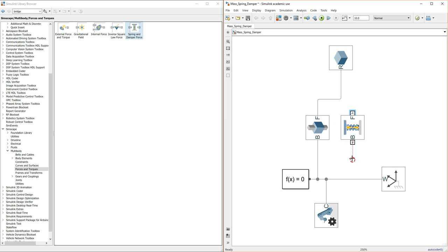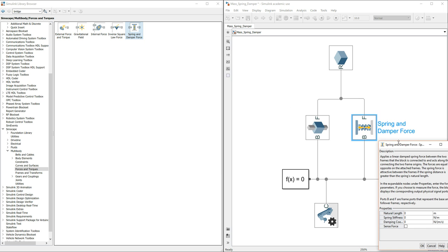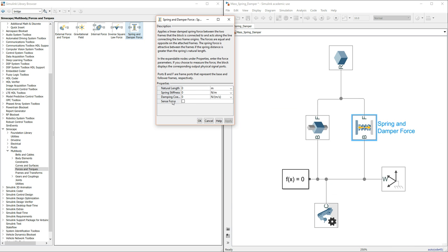What I will do is bring in a connector to here, and I'm going to connect the two across. This connection across is basically saying where the prismatic is acting, you've also got a spring and a damper acting. What we need to do is get these to relate to each other. There is actually an error here, but I'd rather model in the error and then discuss what has actually happened and why. So let's go spring stiffness.